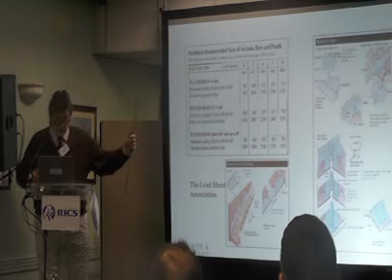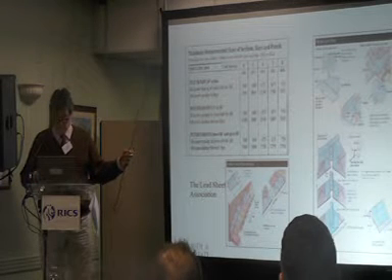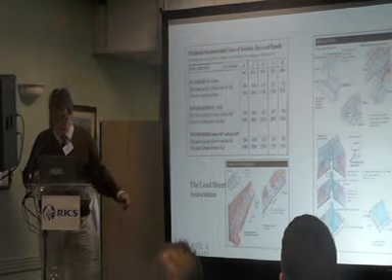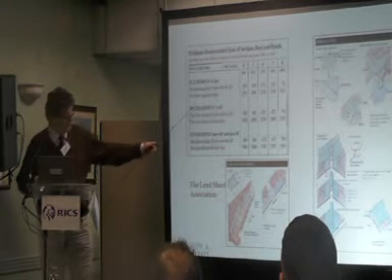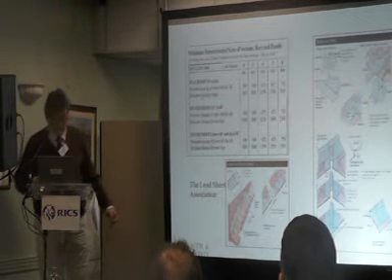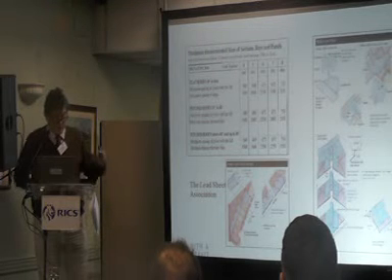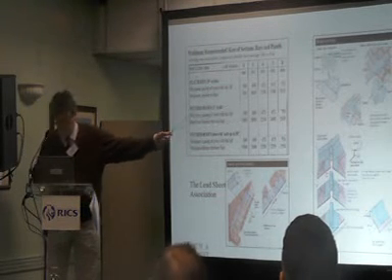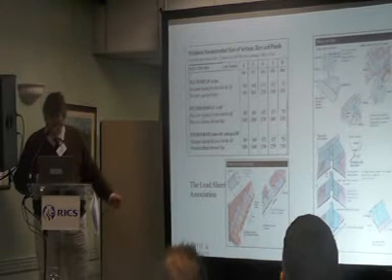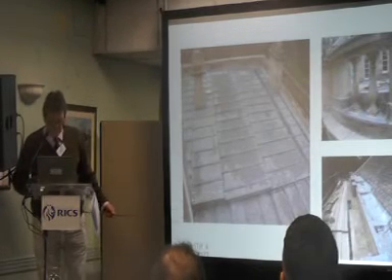Now, do we all know where the coding comes from? A square foot of code 8 lead weighs 8 pounds. A square foot of code 6 lead obviously then weighs 6 pounds. So what you're talking about is the thickness of the lead, allowing you to get extra bay length before you need a drip. So if we look at a roof,